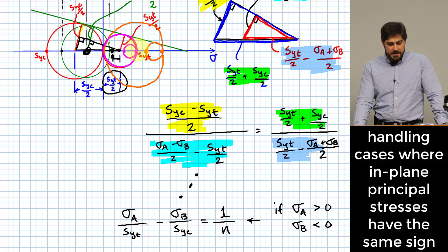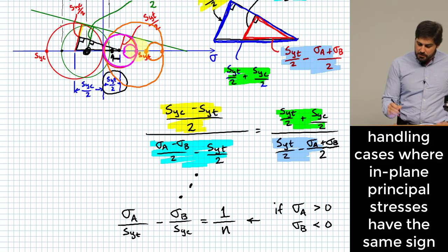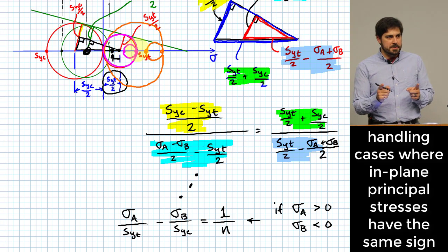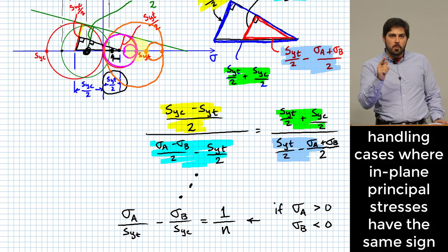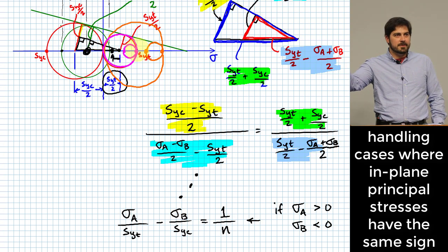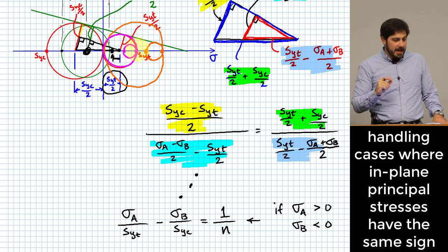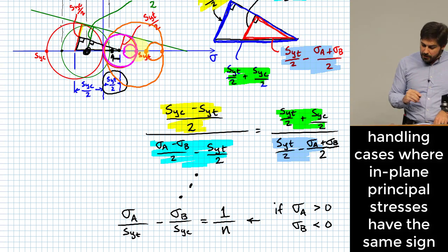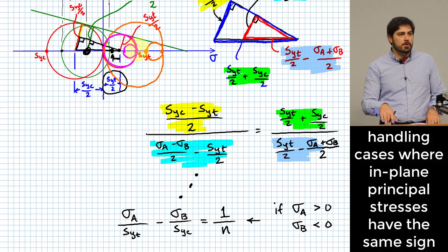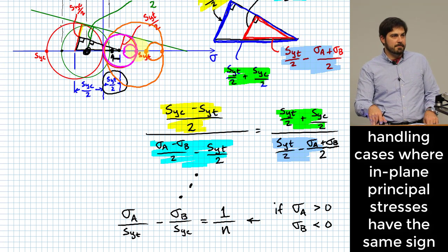So my point with this is that if you end up with a state of stress where both of your in-plane principal stresses are positive, whichever one is the highest one, furthest to the positive on the number line, is going to be the one that controls whether it will fail. And it will do so at the stress threshold that corresponds with the tensile specimen, right?